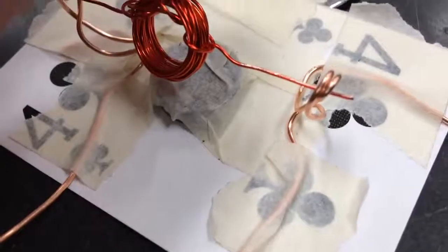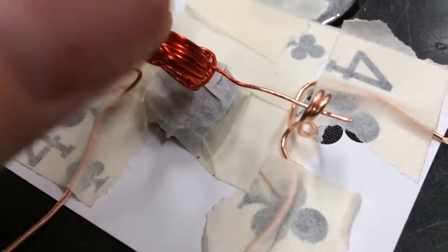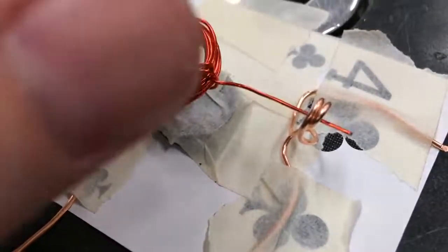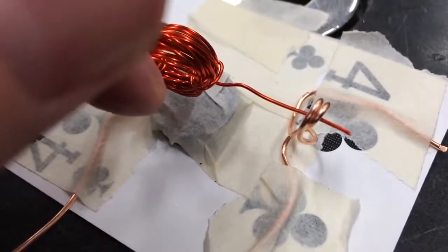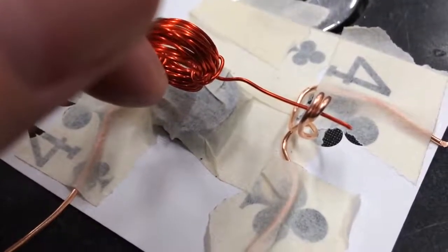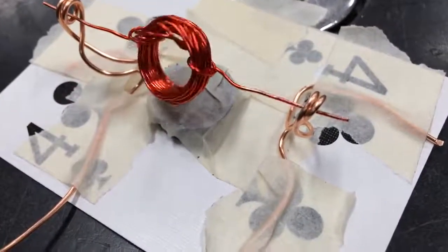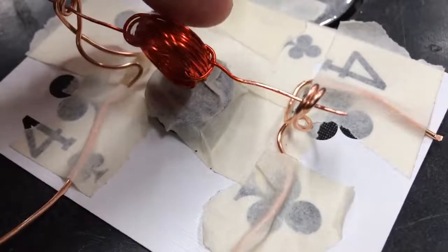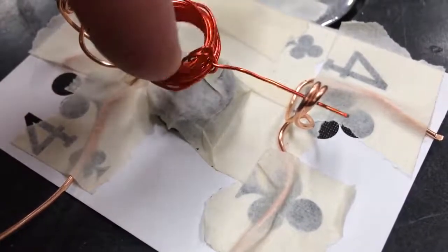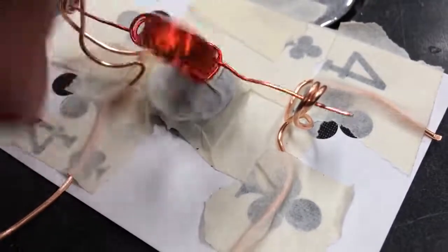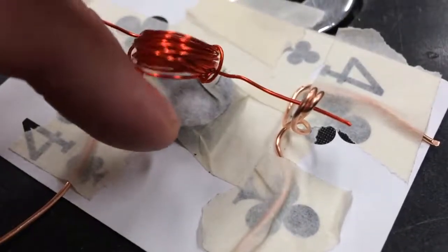If we spin the motor, you can see that half of the enamel's been rubbed away, but the other half is still there. And that means that when the motor's like this, the copper wires are touching and electricity's flowing. But when it's like this, the supports are touching the paint and electricity's not flowing. So in this state, it's actually turned off. But when I flip it over, it turns on. So our motor's only on for half the time.